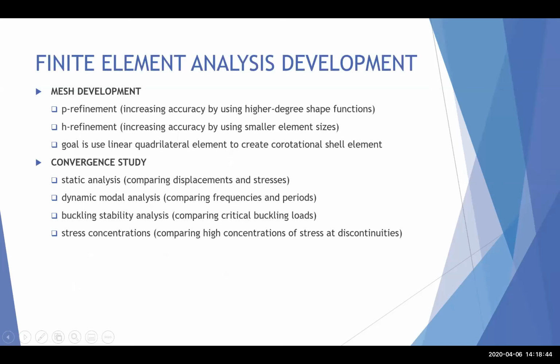This is my last slide, and this is where I'm at right now, where I may need some help with creating the finite element code. The two main things here are mesh development and a convergence study. For the mesh development, I'll be doing a P refinement and an H refinement. For the P refinement, I'm choosing to do linear shape functions first, and then if I get that to work, maybe quadrilateral and quadratic.